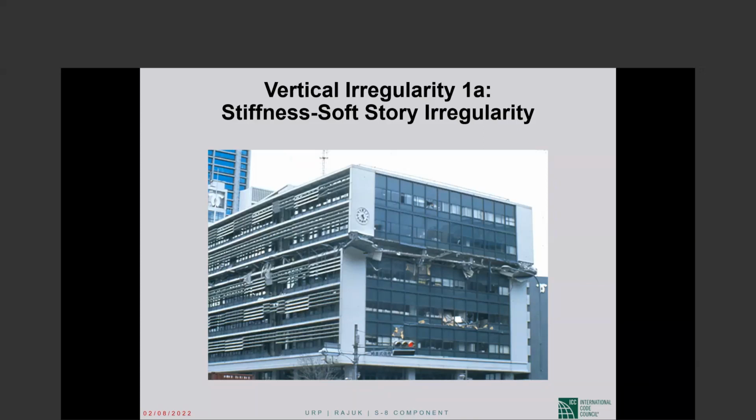You don't need what you need in the lower portions of the building. Your structure can be less stiff. And so they discontinued the structural steel shapes. From steel reinforced concrete, they went to all reinforced concrete. And in the city hall, that happened.